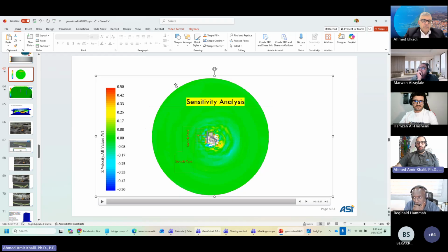And we've had cases where the structures were quite removed from the source, but still they were sensitive. And in this case, the soil model is much bigger. So for such a big model, we would go to a linear elastic. It's justifiable to use a linear elastic model because we're speaking about a really large volume of soil, and the level of vibration is low.